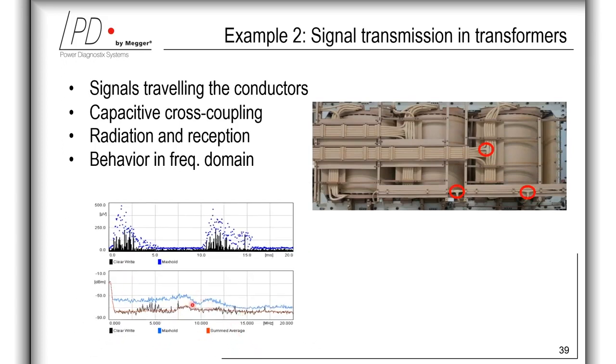The lower graph shows a spectrum scan like the previous one, and the top graph correlates the peak values measured by the spectrum analyzer with their phase positions at a fixed frequency. This is similar to a PD pattern, however, here we have the microvolt range rather than picocoulombs.